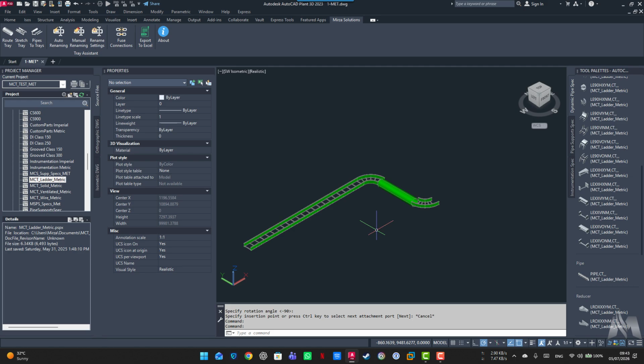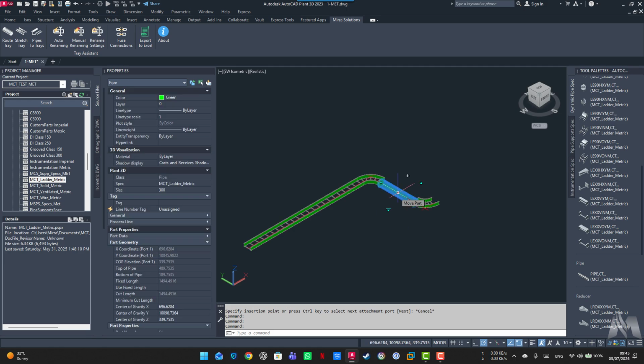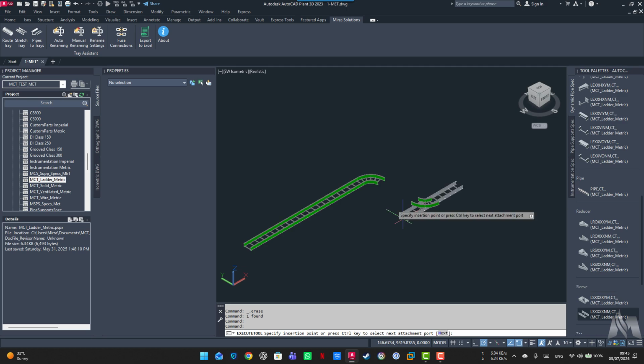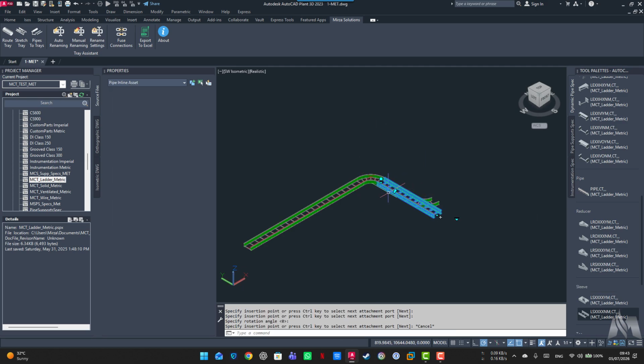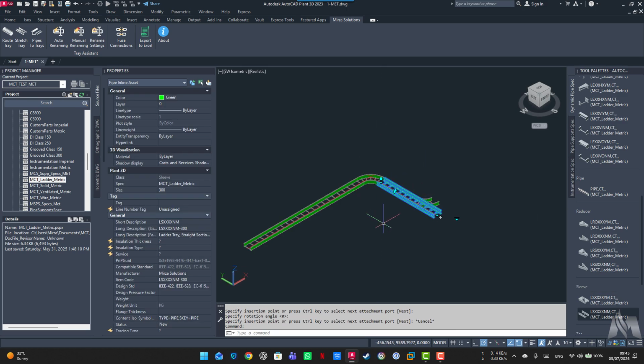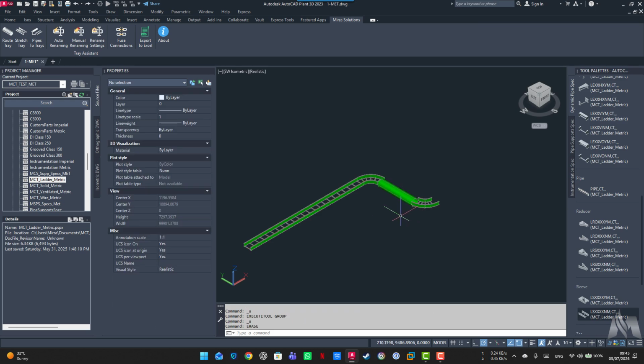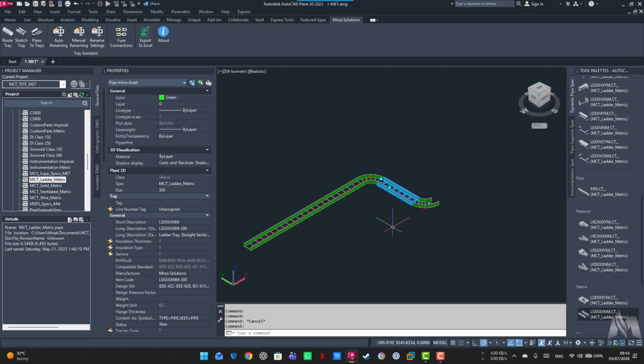So what to do now? One thing is to just delete it and put in the cable tray section over here and make the changes of the size and make the adjustment. This is a long process. But this third button over here, if you simply click it, what it does is basically scan the model and find all the pipes that belong to the cable tray system, and it automatically converts them to their corresponding trays. You see, now that pipe is being converted to the cable tray.